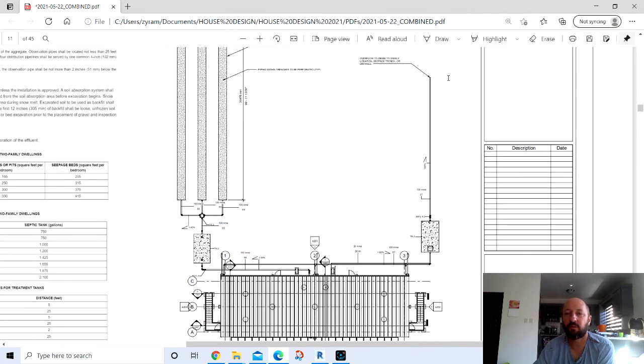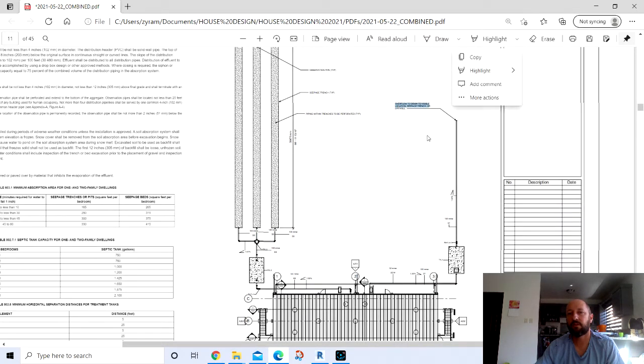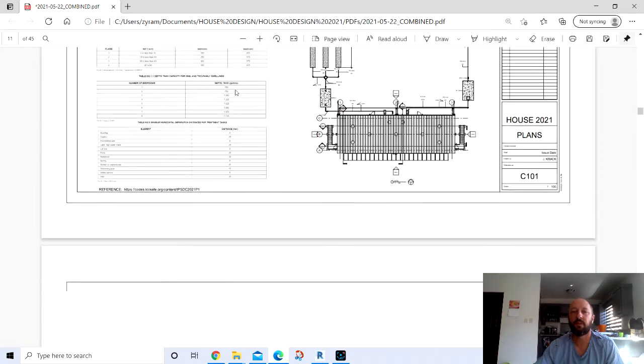Oh, this is just the overflow. There wasn't a drain. I'm not sure how you're going to clean that out. But anyways, we'll worry about that later. If you're on a hillside, it opens up to... I meant to add a detail for a dry well. But anyways, you'll either have to add a dry well or a seepage bed or something if your site doesn't slope to drain.